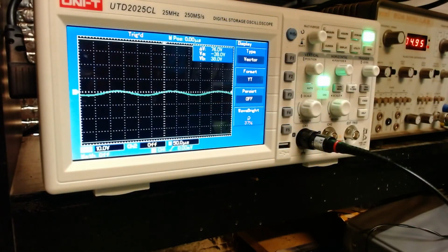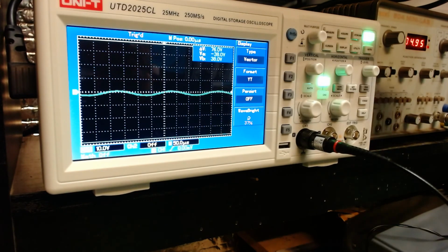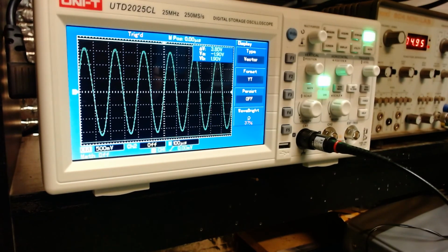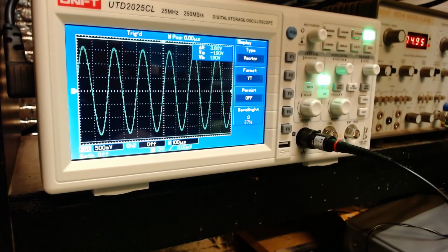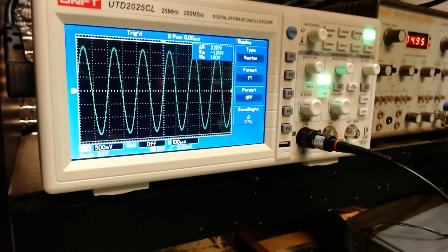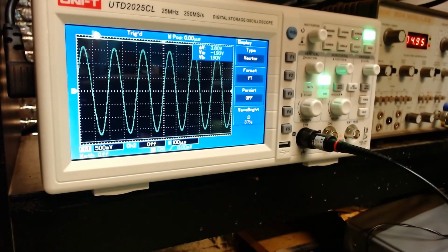Okay, so I'm looking at the waveform across the capacitor now, and I haven't got much of a waveform there. As I said, if I hit the auto button, it goes through a bit of a sequence, and there we go. It pops up with the waveform for us. So easy to use. But you need to know and understand how to use a cathode ray oscilloscope so that you can use a digital storage scope and all its features as well.